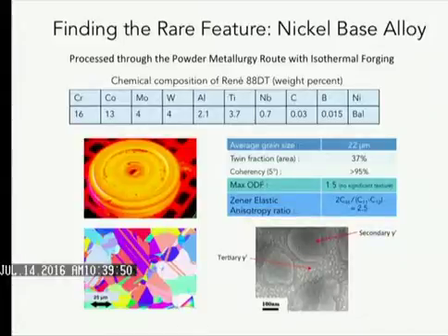Going back to our aircraft engine, this is the turbine disc, the safety critical thing. You don't really need to know any of these details other than these are kind of complicated nickel alloys. And they are polycrystalline in character. They have these special features in the grains known as twins, so it's just a special crystallographic orientation to the material around it, and they're highly elastically anisotropic.